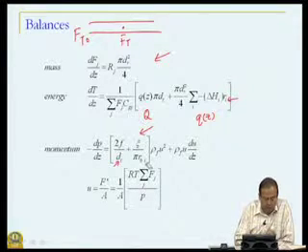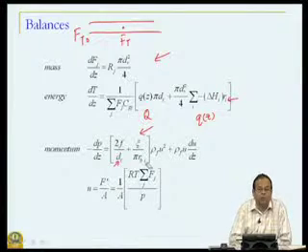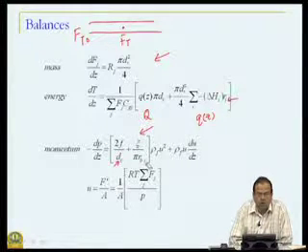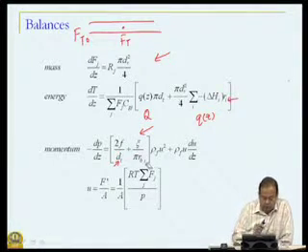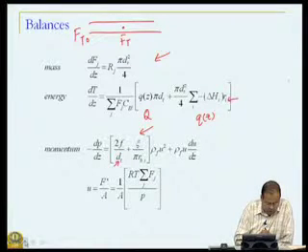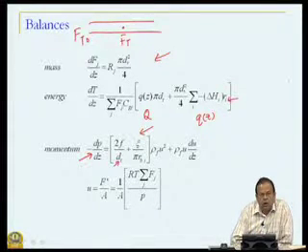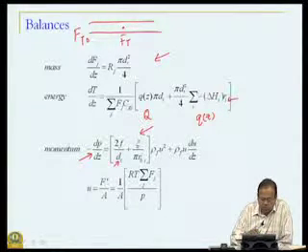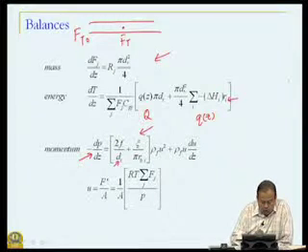Okay. Let us start with the momentum balance. Now, one would think that why should the momentum get influenced by how the mass is changing in the reactor, but when we have the chemical reaction with change in number of moles, they are indeed connected. Now, how? You look at this pressure balance or the momentum balance, where this term tells us how pressure is changing along the length of the reactor, and this has velocity term and density term and so on. Now, what is the velocity?